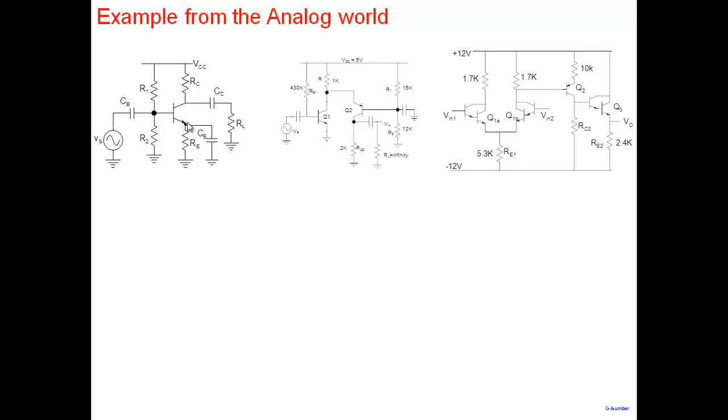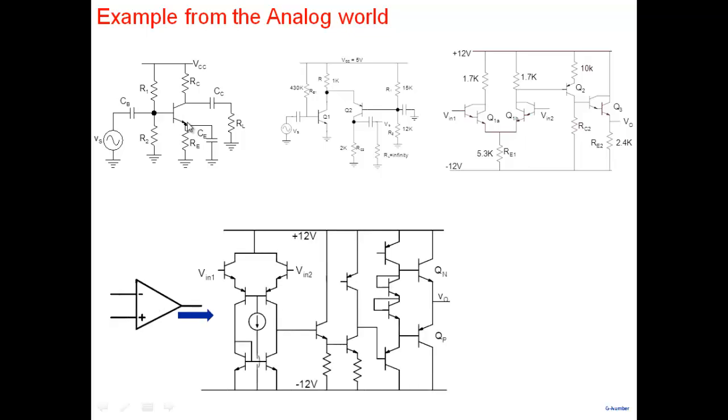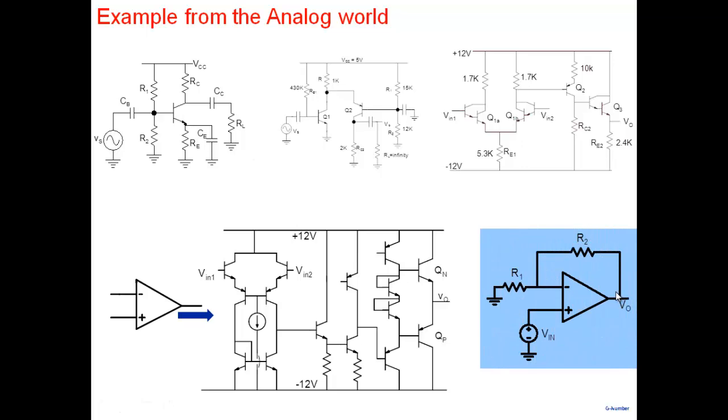The solution that all of you have seen. Op-amp. Op-amp was the solution. Let me make a general purpose amplifier, a general purpose, fairly complicated amplifier, which I can sell in millions. And now this guy who wants a gain of 20 comes in, and how does he customize the solution? He takes the op-amp, and the customization is done by adding 2 resistors of appropriate values.